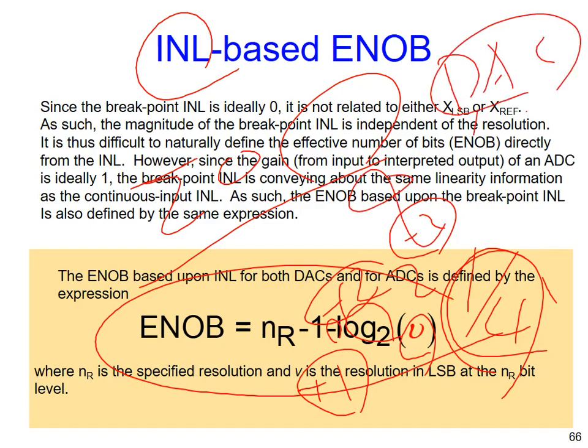For such kind of sigma delta ADC, people usually claim the ENOB is more than 20 bits, right? But how about the DAC embedded inside? Usually 1 bit, 2 bits, maximum 3 bits. Really hard to design. With 3 bits, really, really hard. Usually only 1 bit or 2 bits at the most.